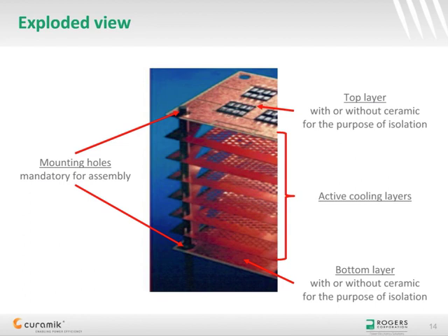Mounting holes in each layer are used for a precise alignment of all layers during stacking. The stacked layers are then screwed all together during the following bonding process to avoid relative displacement in the high temperature furnace. Screws are removed after the bonding process.